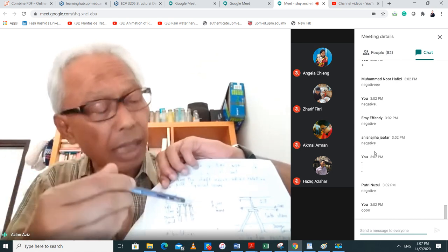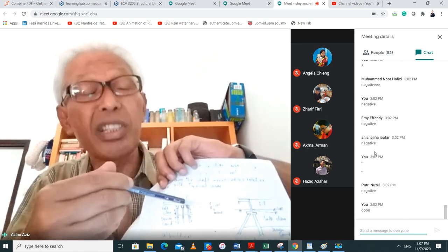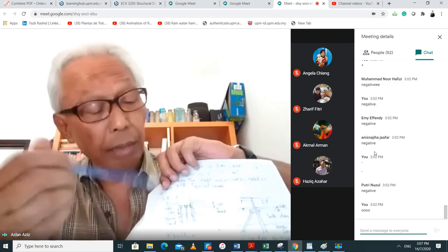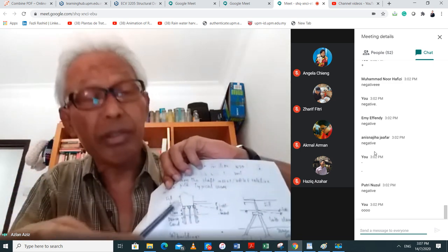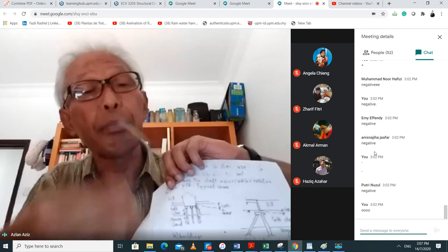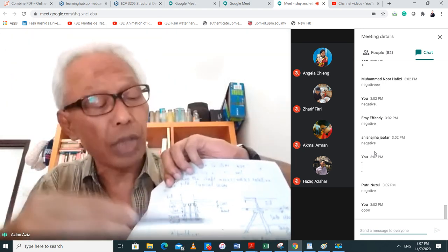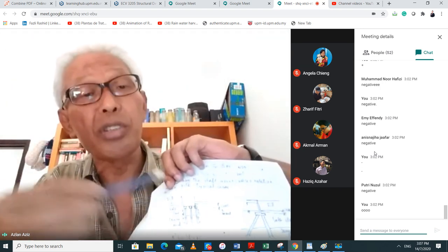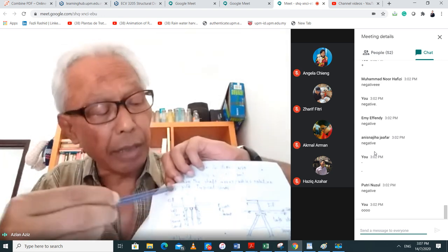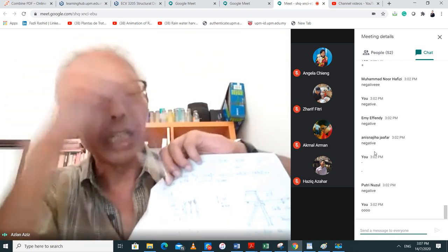Say nothing happens to it, you put fill, it is stiff clay, no settlement. So the skin friction would still be positive, because no settlement is pulling it down.